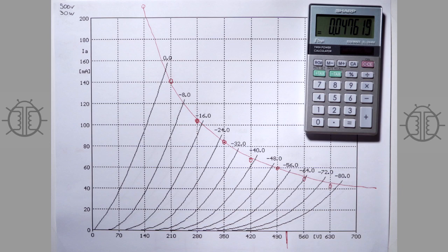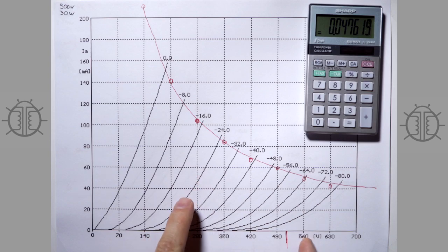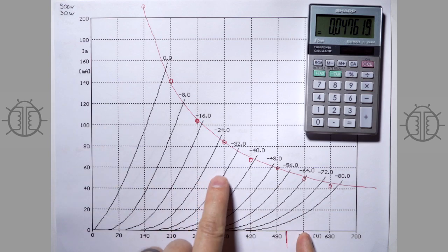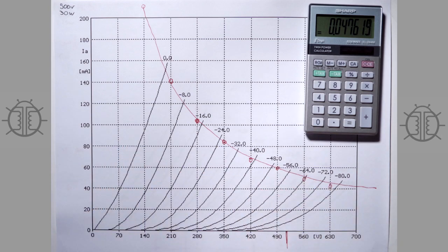I mean, 400 odd volts, 500 volts is not that low, but it's much better than trying to get a supply up here, like with a resistive load, and then having to swing up and down from there. You can start up here. Anyway, that's how output transformers work. They're inductive, and they will allow you to swing above. Whatever your supply voltage is, there'll be a little bit of DCR in the transformer primary, so your voltage will probably be 5 volts below supply voltage, but for all practical intents and purposes, it's going to be your supply voltage.